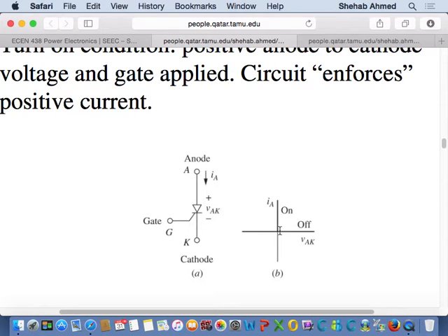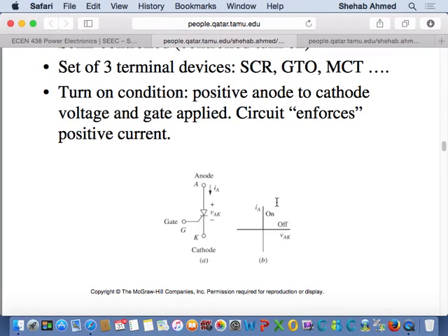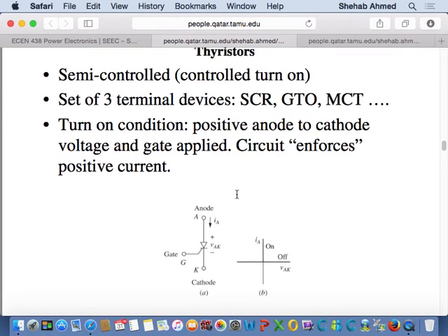And behave like a diode. It will behave like a diode until you try to push current through it in the opposite direction. If you do that through a diode, what's going to happen to the diode? It will block. Current cannot flow in a negative direction through a diode. So as soon as you try to do that, or the current goes to zero and tries to flip direction, it blocks. Okay, so that's an SCR. People call them SCRs or thyristors, it does not really matter.